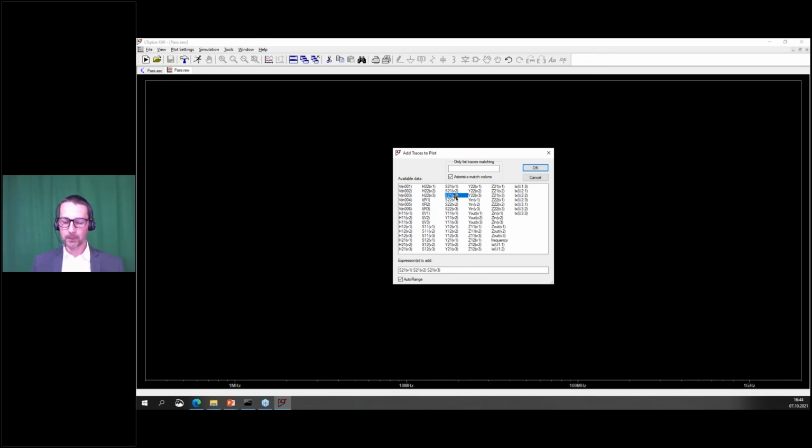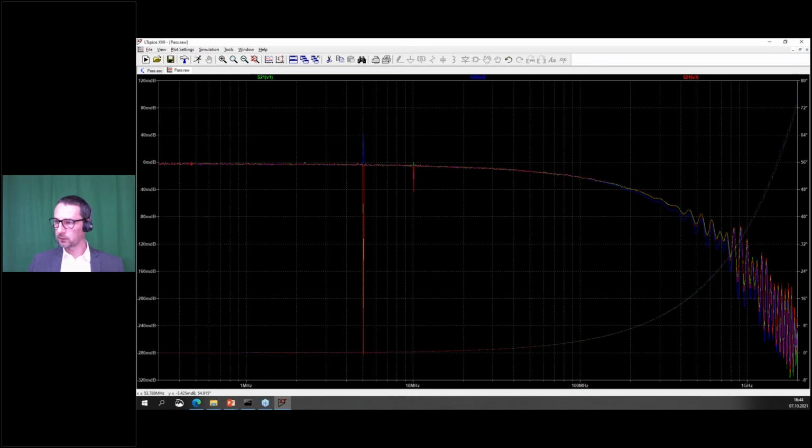If I measure the insertion loss of one transmission line in 3 different layouts, and we said we shift the reference point to the pins top and bottom, so that we really only measure the connector, they should be very similar. Of course, there will be some deviation depending on the soldering, manufacturing tolerances, all that kind of stuff, but they should be very, very similar.